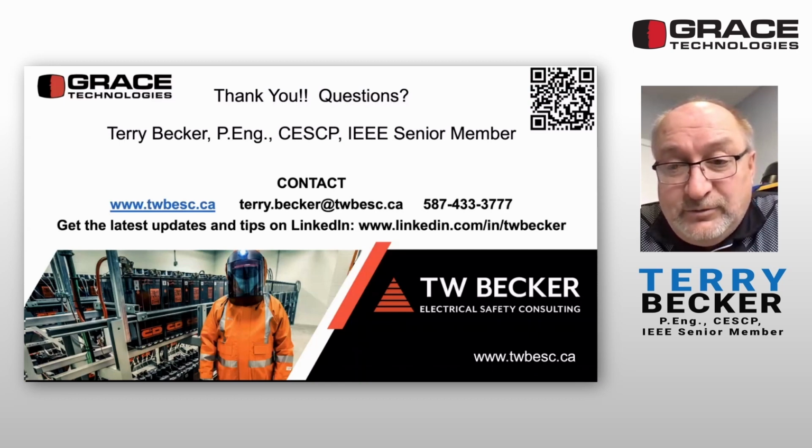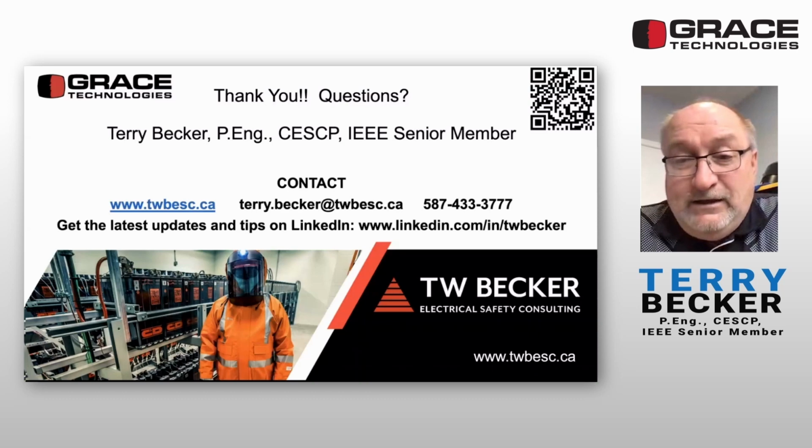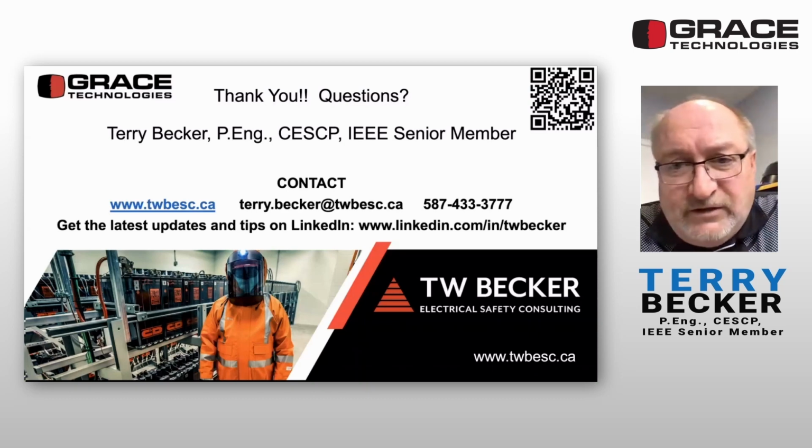So many manufacturers are creating so many requirements to protect against arc flash and shock on panels when the feed is off. Is this potentially due to misinterpretation of the code regarding arc flash? Because they also typically require finger safe terminals to protect from shock. Yikes. So treat the hazards separately.